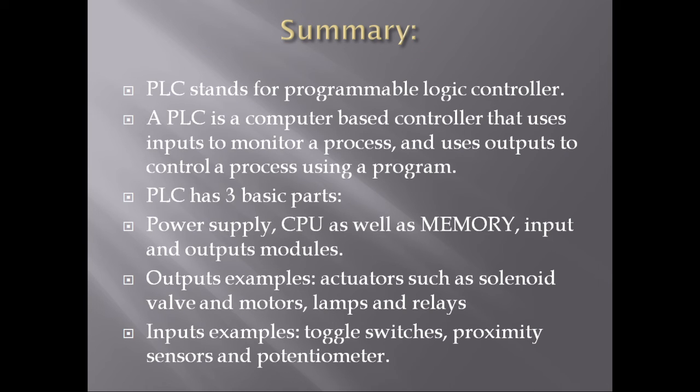Summary: PLC stands for Programmable Logic Controller. A PLC is a computer-based controller that uses inputs to monitor a process, and uses outputs to control a process using a program. A PLC has three basic parts: power supply, CPU as well as memory, and input and output modules. Output examples: actuators such as solenoid valves and motors, lamps, and relays. Input examples: toggle switches, proximity sensors, and potentiometers.